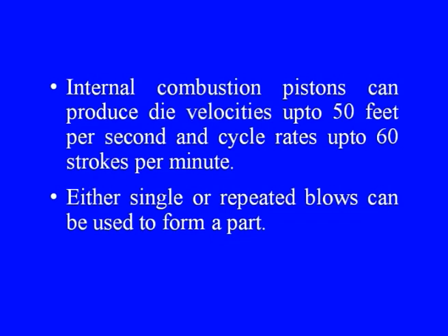Internal combustion pistons can produce die velocities up to 50 feet per second and cycle rates up to 60 strokes per minute. Either single or repeated blows can be used to form a part.